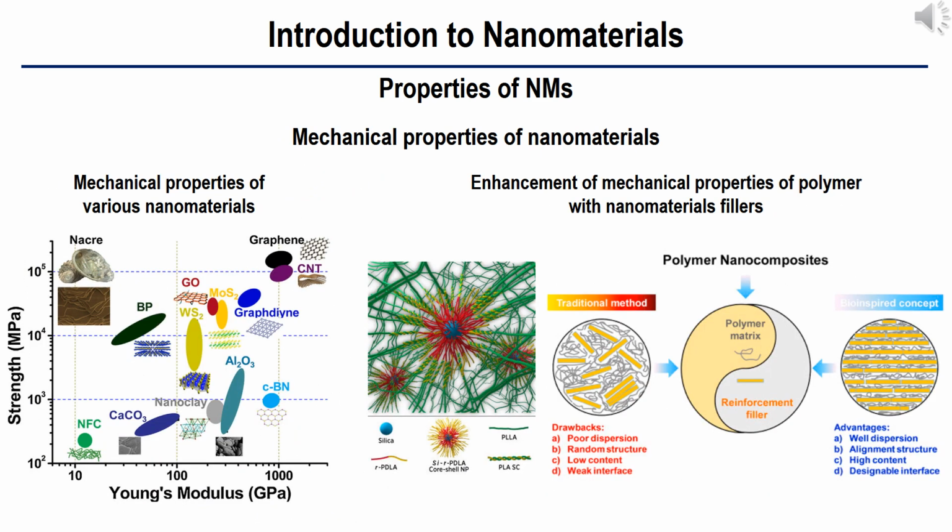In principle, we can expect the enhancement of mechanical properties of materials at the nanoscale. This is mainly because nanoscale materials can reduce the grain size, increase the structural disorder and surface of grain boundary, and make more barriers for dislocation movement. These factors make materials mechanically stronger at the nanoscale.